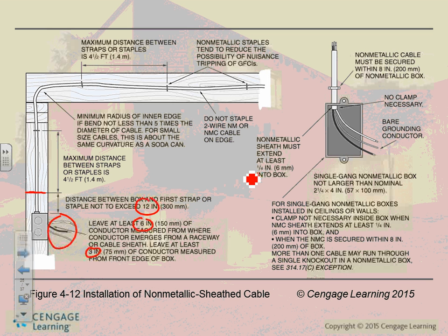So these are rules. Number 3, 4.5 feet in between. Can you guys see in between, 4.5 feet, 4.5 feet, 4.5 feet? When you support them or staple them, you have to support them every 4.5 feet. That's it. These are the rules of Romex and NM cable. So when your project manager walks away, you look at the Romex, you do your inspection before the inspector comes.